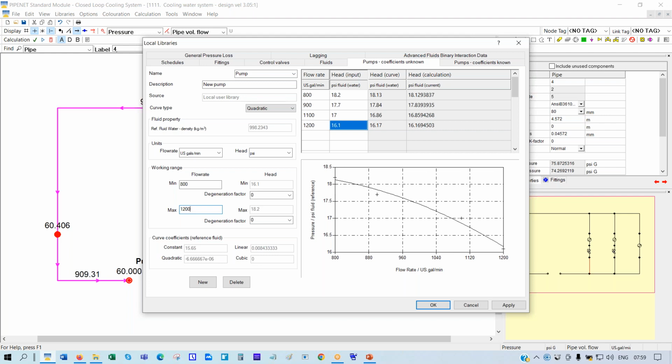The pump can freewheel. For example, if you have a pump which is connected to a holding tank, and on the outlet side, the discharge flange is not connected to anything, what do you think that pump will do? It'll work above this flow rate.